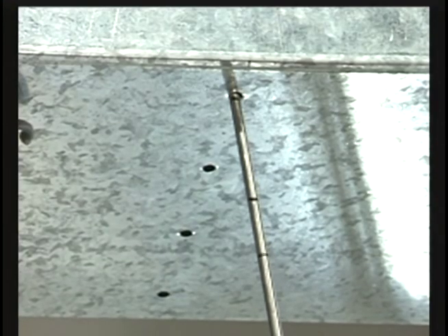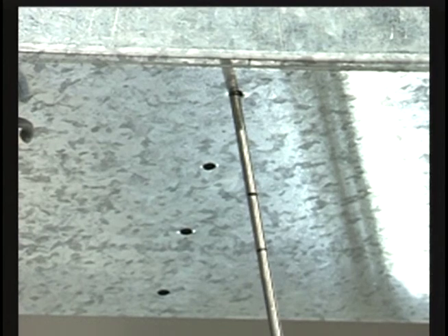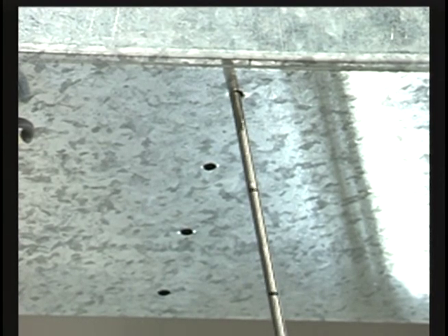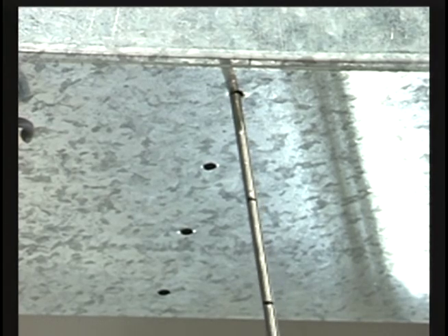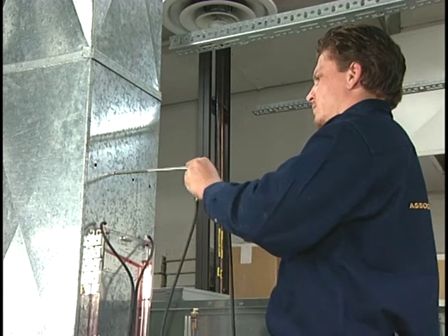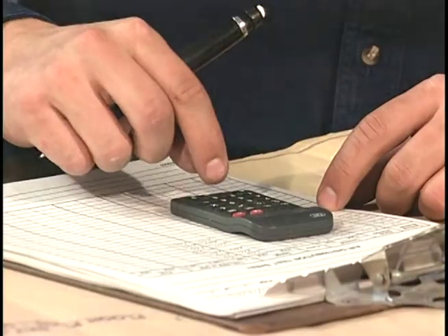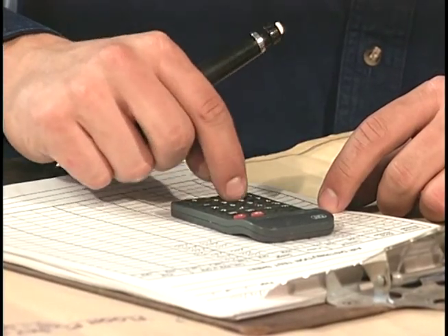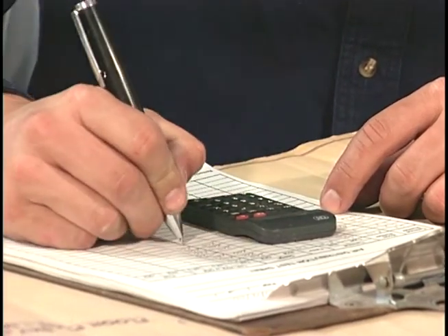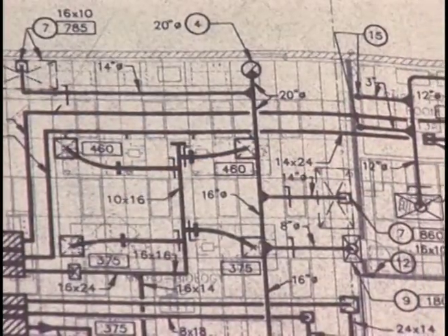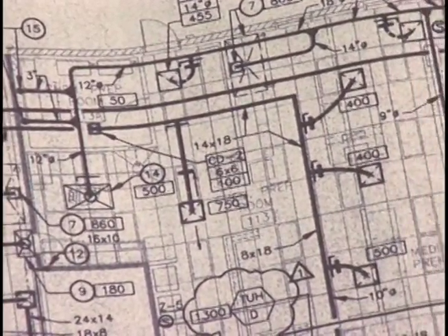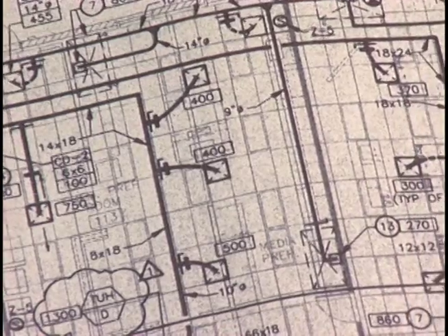After setting up the fan, the next step is to measure the system's total air. One way to get total airflow is to take a pitot tube traverse in the main duct. A second method is to traverse each of the duct branches and add the results. A third way to get total airflow is to traverse the return and outside air ducts and add the two totals together. A fourth method is to read all the outlets and add the readings together to determine total air.